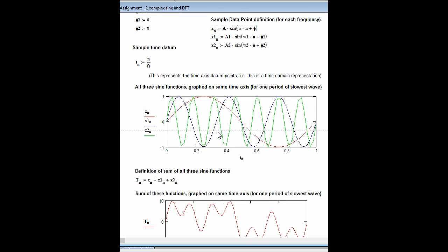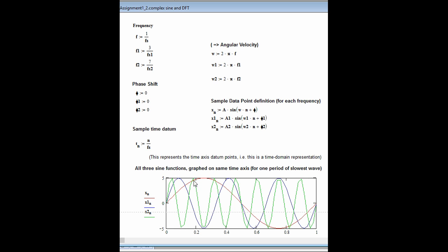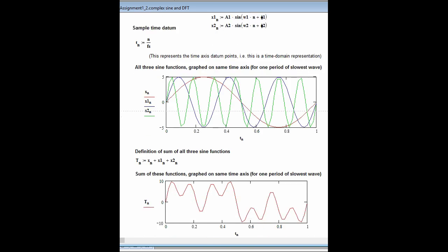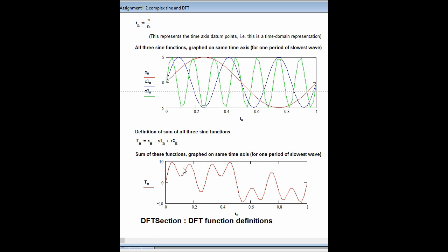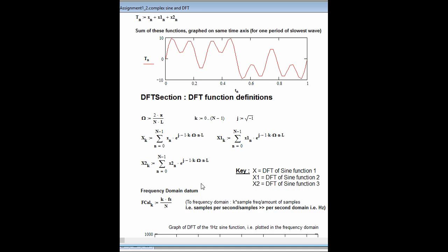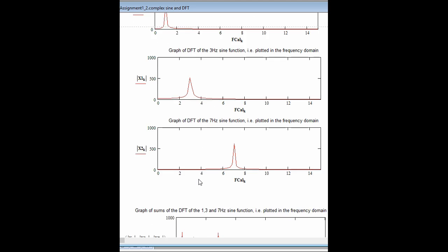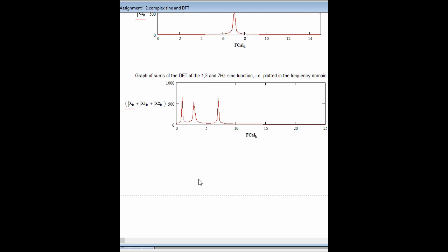This is just a simulation. If that's not the information you're expecting, but you're getting something like this, it means there's a noisy part on it. In this case we did a discrete Fourier transform, or you can also do a fast Fourier transform. Doing a fast Fourier transform brings you into the frequency domain.